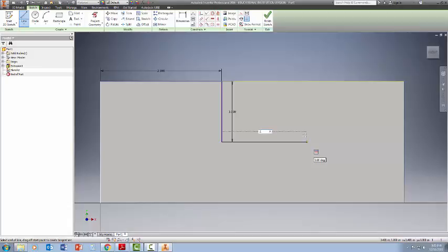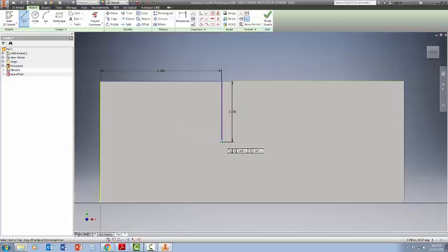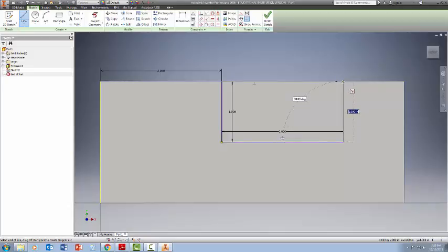What I want to do, real quick, is right click, repeat line, and make sure that I'm still doing the degrees correctly. You see how it says 0 degrees? It'll either say that, 90, or it might even say 180, but as long as it's flat. So I'm doing 2, enter, and then because it's still attached, I want to make sure it comes up 90. I'm just scrolling up, and it says 90 degrees on the left hand side. Now it says 86.